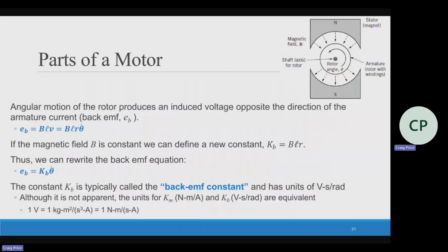Unlike the other electrical machines, DC motors exhibit a unique characteristic: the production of back EMF. A rotating loop in a magnetic field will produce an EMF according to the principle of electromagnetic induction. The case of rotating armature loops is also the same. An internal EMF will be induced that opposes the applied input voltage. The back EMF reduces armature current by a large amount. Back EMF is proportional to the speed of the motor.